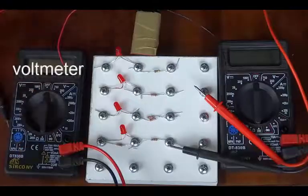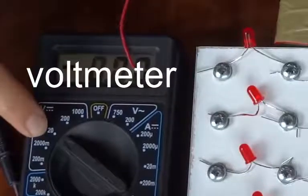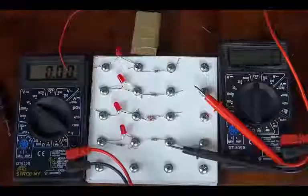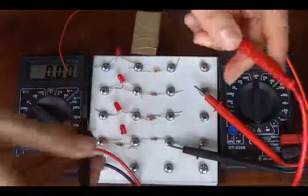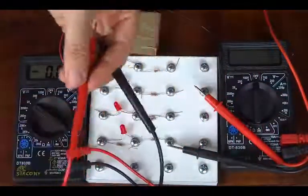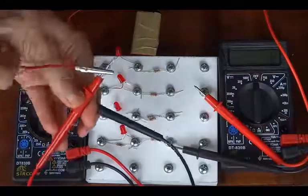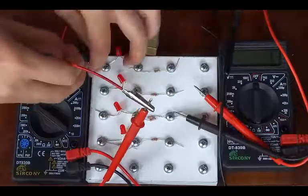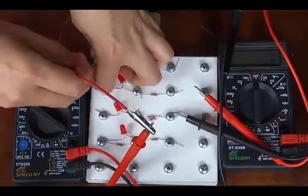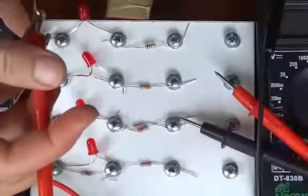So this is going to be our voltmeter. Let's set it on the voltage maximum 20 volt setting. And it has to be in parallel across the LED in each case. So I'm going to use some crocodile clips to help me. I'm going to use this red crocodile clip on the red probe, on the positive probe. And I'm going to connect that over here to the LED, to the positive side of the LED.